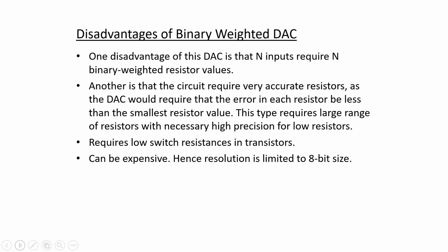For this particular design, the n different resistors are supposed to have values which are quite precise and accurate, so that they are in equal weighted proportion. If there is too much error in the values of the resistance, then the ratio between two branches will change, and ultimately the final converted output voltage is not going to give an accurate result.